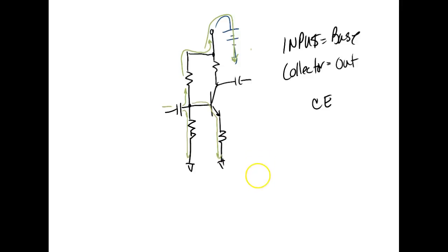Okay. So my AC input is actually like this. I come in through my capacitor. I go through R1. I go through R2. Then I go through my transistor and then RE. But RE is seen as times beta. That's the input circuit right there. That's exactly what your input is. So that means I can calculate that input resistance right there. Y'all understand that?